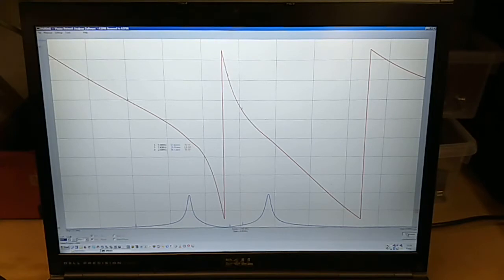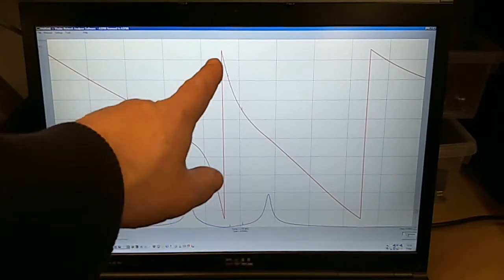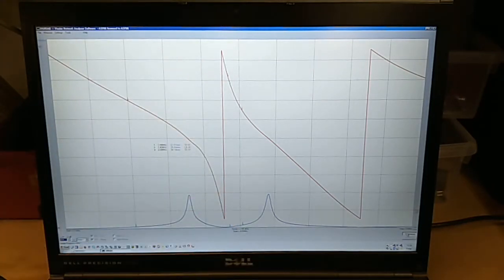So now there is a balance one can consider. Well, why isn't the tank capacitor resonant circuit arranged to be at the same resonant frequency as the secondary? Now there is a balance between coupling as much energy between the primary and secondary as possible. That's based upon obviously matched frequency resonant circuits, but also the amount of energy that's stored on the tank capacitor.